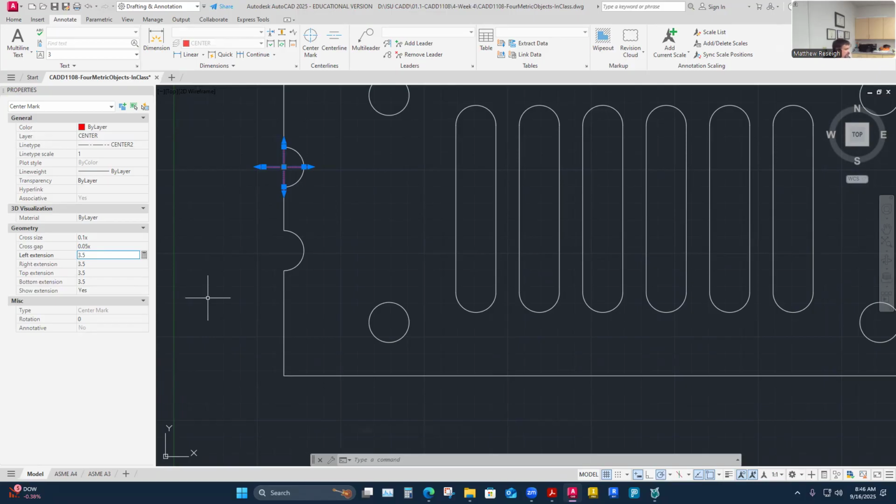1/4 inch in metric is 6 millimeters, roughly. We don't want to use six and some decimals, so we're just going to use 6 millimeters. So technically, to replicate the ASME standard in this, it should be 6 millimeters. So I'm going to say six over in the properties panel instead of 0.25 like we've been doing. It's actually six, six, six, and then six again.